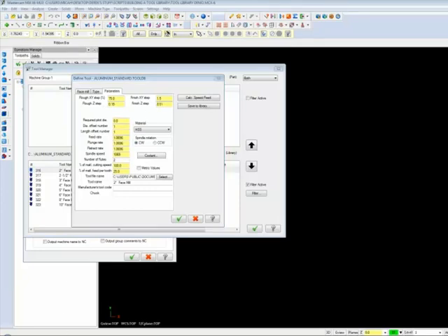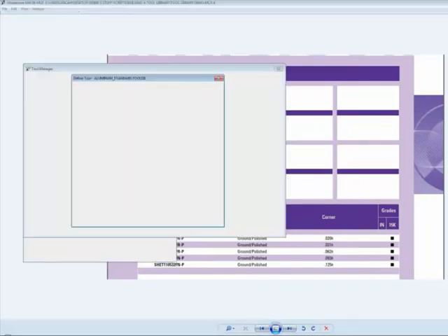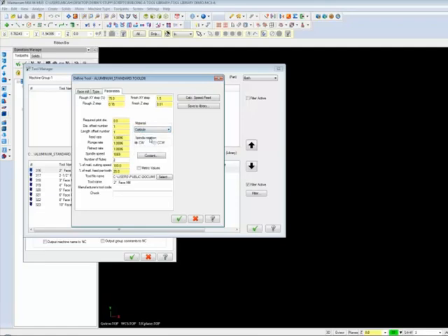The inserts are made from carbide, and there's 5 of them in the tool. Go ahead and select carbide as our material and enter 5 as the number of flutes.